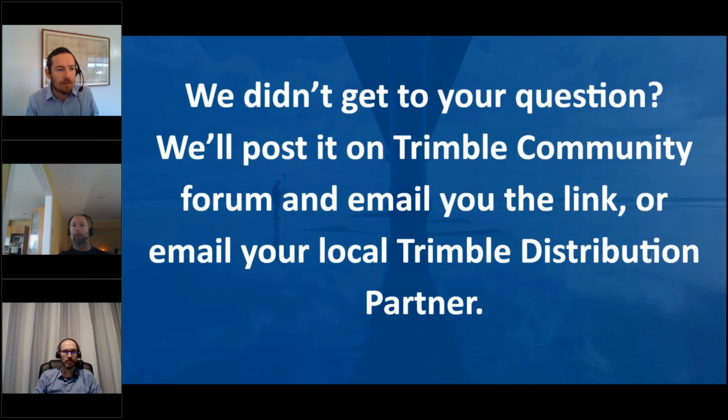So I'm actually just going to open up my Trimble Access. Unfortunately, you guys can't see this, but if anyone's used Trimble Access 2020, you'll now see the terms global reference datum, and you'll see a global reference epoch. So I'm looking at a New Zealand coordinate system in front of me on the screen at the moment. And in New Zealand here, we use a 2000 datum, New Zealand Geodetic Datum 2000. So the epoch is 2000.